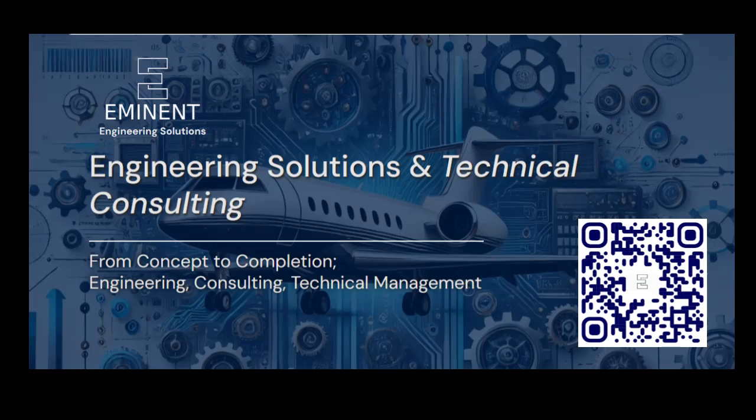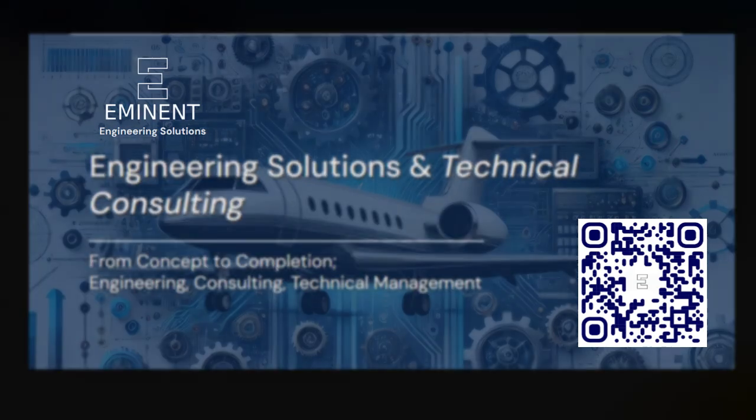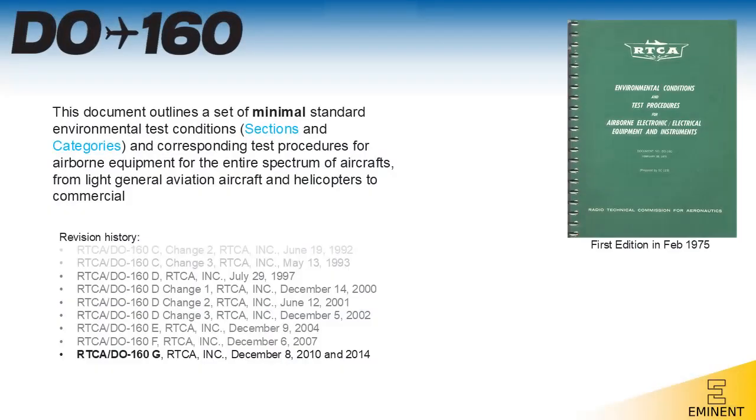DO-160 Revision G, 2010. This current revision is the most comprehensive, adding or refining sections to address modern environmental conditions and equipment susceptibilities, such as electrostatic discharge, icing, and power input resilience. With each revision, DO-160 has adapted to address new environmental concerns, ensuring it remains relevant for both existing and next-generation aircraft systems. The role of the FAA in DO-160 standards.